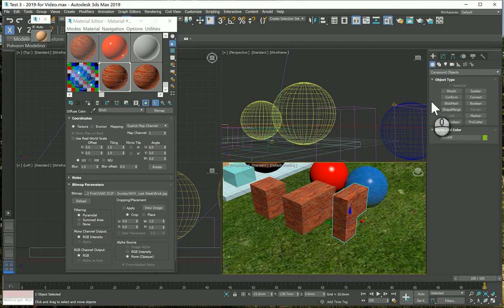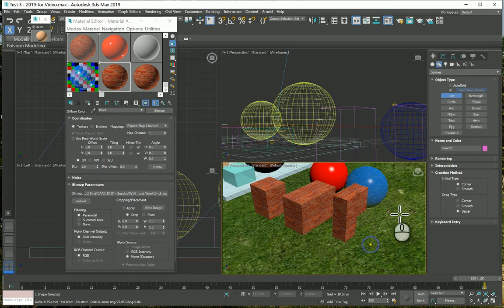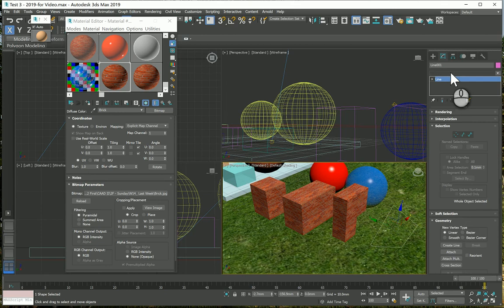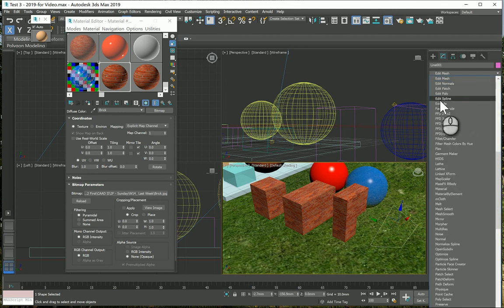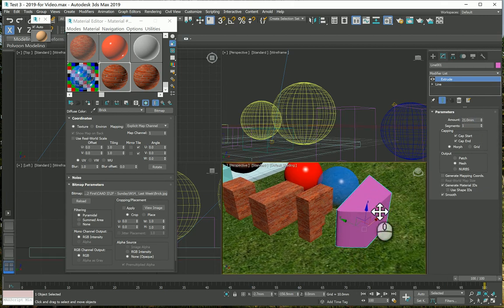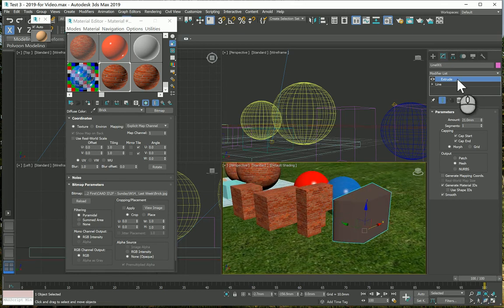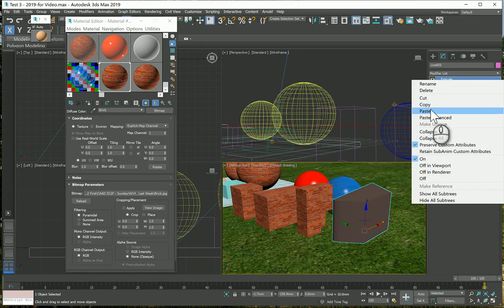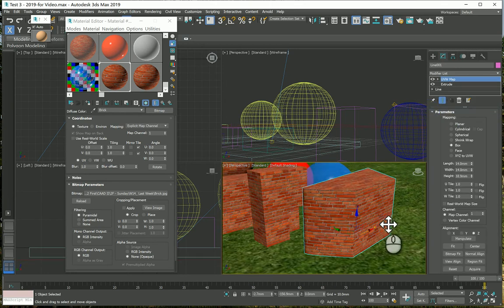Also, you're going to face it when you have elements that came from 2D shapes like this one, and when you extrude them. Let's go ahead. I mainly also face that when you give those walls, but I'm too lazy to do that. Usually you're also not going to see the thing immediately when you add it, and you have to right-click and paste the UVW map that I copied from here in order to see it.